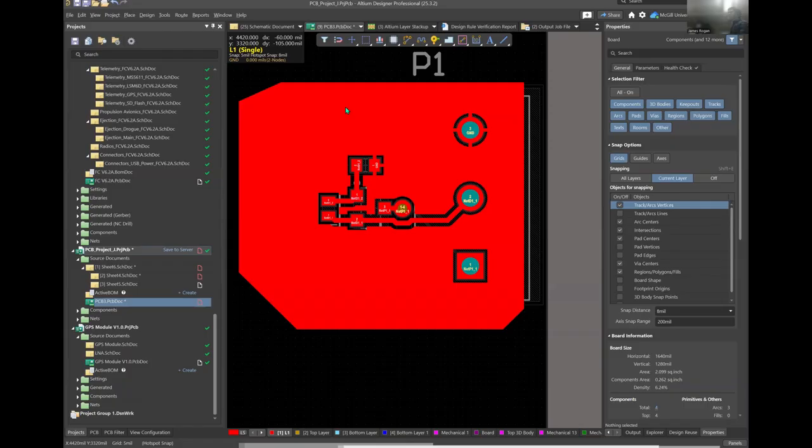Okay. So for example, on this power supply here, there's a black terminal and a green terminal. The black terminal is your 0 volts, and then your positive terminal is whatever voltage you apply. And this ground here is the chassis, and it's connected to the grounding lug on the input connector. So there's two sorts of grounds. There's the 0 volts, which is your signal ground, and then if you're working with mains power systems, you have your earth ground.